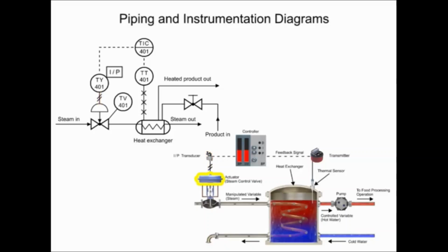The pneumatic control diaphragm actuator that opens and closes the globe valve regulates the steam in the process. The actuator is represented by the half circle in the P&ID. The arrow pointing downwards from the actuator indicates a fail-closed valve type.